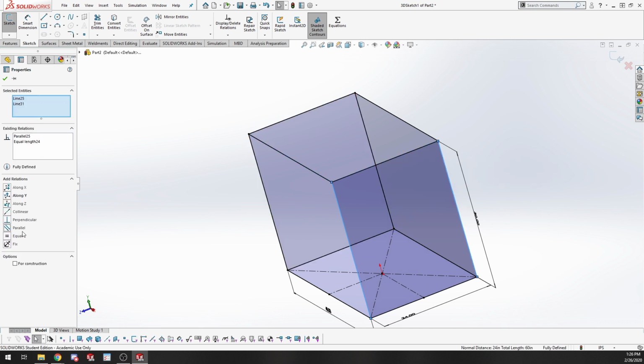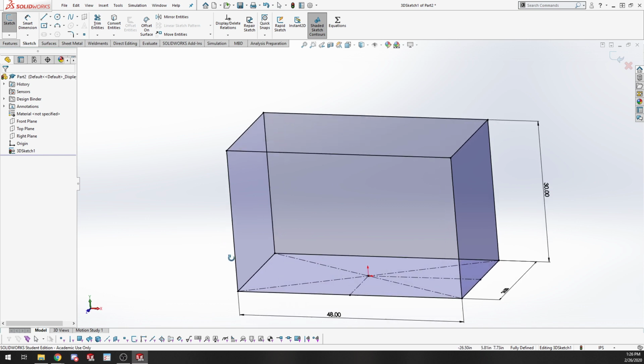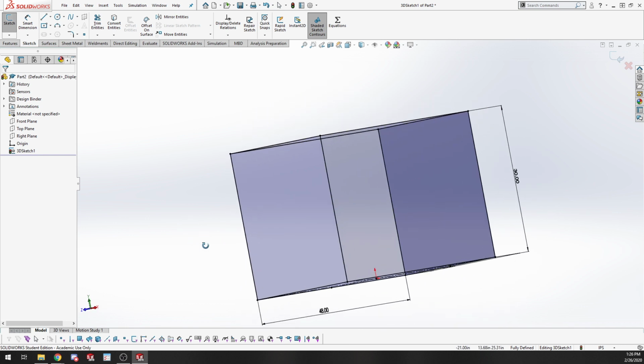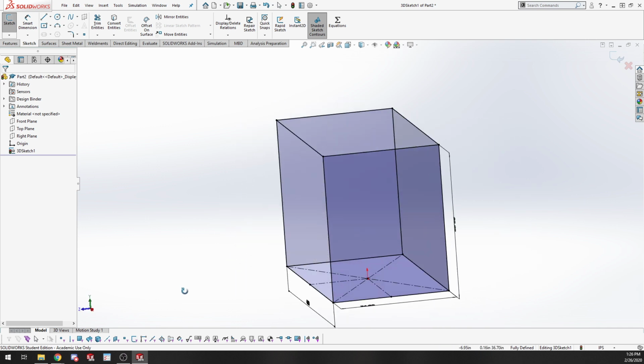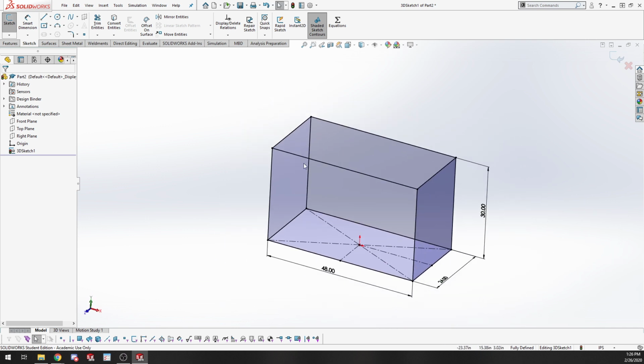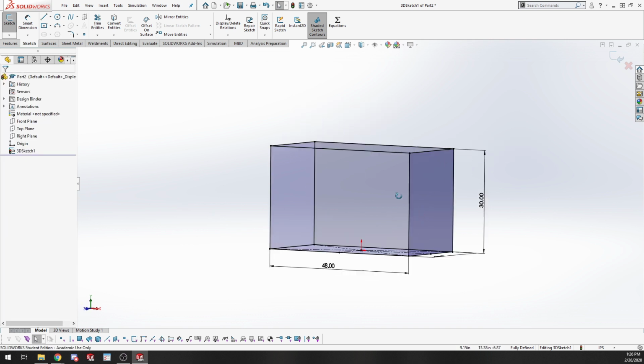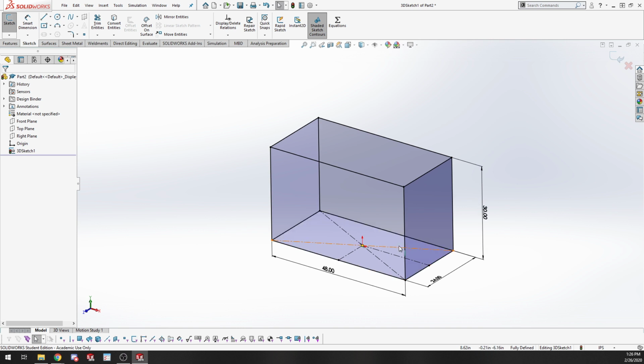Equal length and parallel. Alright, there we go. So SolidWorks, we're just trying to really fine tune those last couple of points. But just like that, 3 dimensions, a lot of relations: parallel, equal length, along X, perpendiculars. So you really have to be careful as you're adding in these relations. Really just draw your lines out, add them in, define them, then move on to your next stuff.